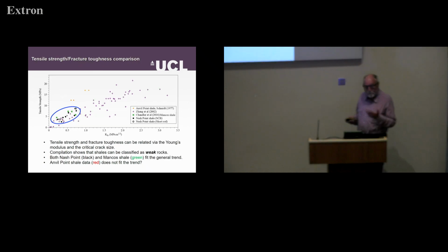So we can relate the tensile strength and the fracture toughness to each other, theoretically, just by considering the elastic modulus and a critical flaw size.